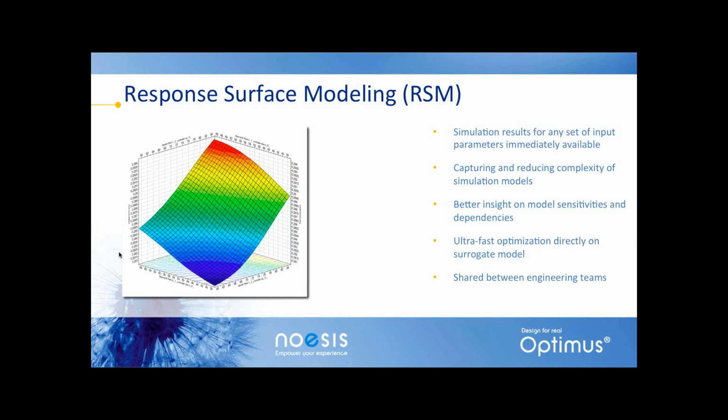This response surface, by the way, goes by a number of different names, sometimes called a meta model, approximation model. This is extremely powerful because now, after running your DOE, you can get parametric data in less than a second, and in fact can be run on a cell phone processor. Anybody in the organization can now do parametric studies based on that model. So the response surface model, which Taylor will talk more about, is extremely powerful. It allows you to greatly speed up your analysis.